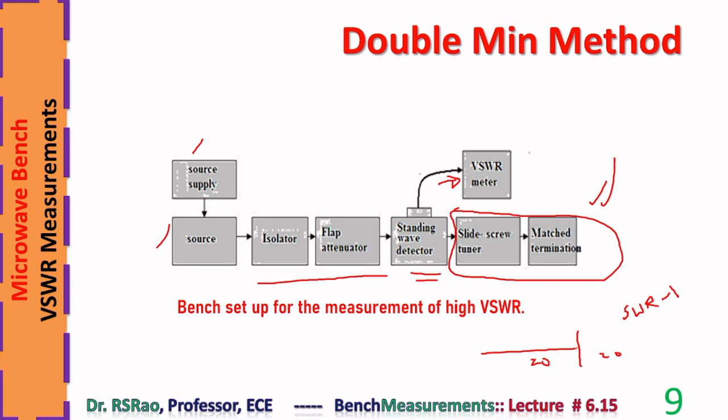Then what to do? Insert a certain impedance between the line and the load, somewhere here. Now the line sees an impedance which is different from Z0. Because of the insertion, the terminating impedance is no more Z0. Hence, reflections happen and a standing wave pattern comes into being.